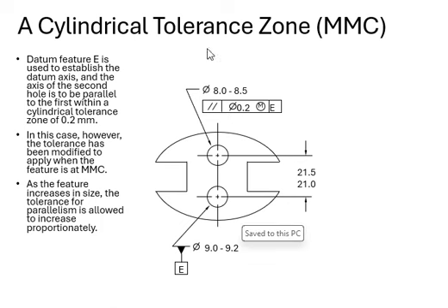So here's a cylindrical tolerance zone with your maximum material condition here, and we are dealing with this tolerance zone. We're referencing the entire 360 degrees around, so you're dealing with the diameter for that. Okay, this is all I need to point out for this.